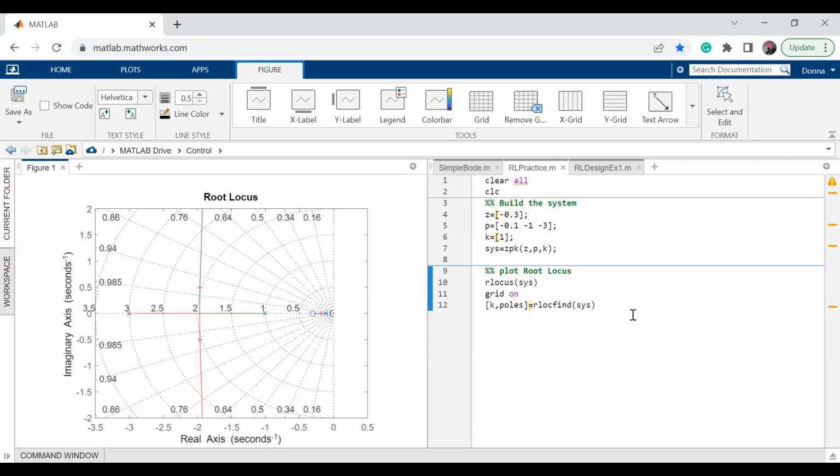So you are thinking in terms of frequency. That's why Bode plots are so important, because you see the frequency response right away. I'm going to assume that in your 2020 course you plotted Bode plots. From there, you should be able to tell from the slope of your Bode plot how many poles your system has. There are also ways to find where those poles are. So a Bode plot could be sufficient to find all the information. What frequencies are of interest? Okay, let's see what happens at those frequencies. All right, cool. Well, I'm excited.